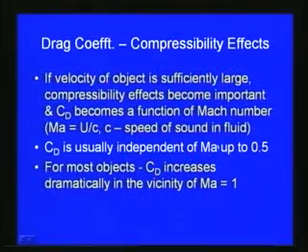Especially for the flow we consider, if it is a fluid like water, then the effect will be very negligible, but if we consider airflow, then the compressibility effect will be much higher, and when the Mach number increases to 1, the coefficient of drag increases dramatically. But up to about 0.5 we can show experimentally that there is not much effect on the coefficient of drag with respect to the compressibility of the fluid.